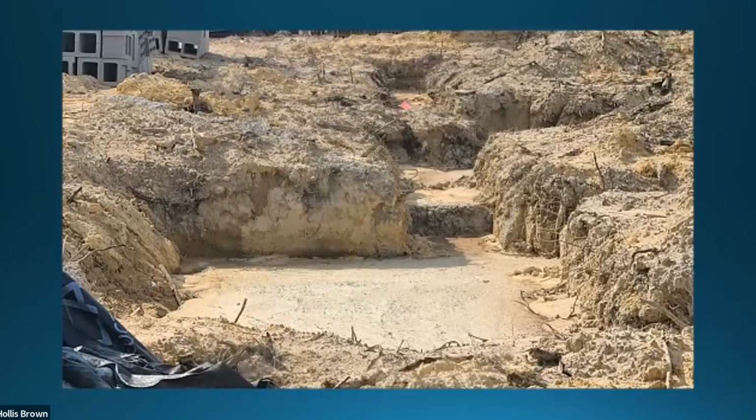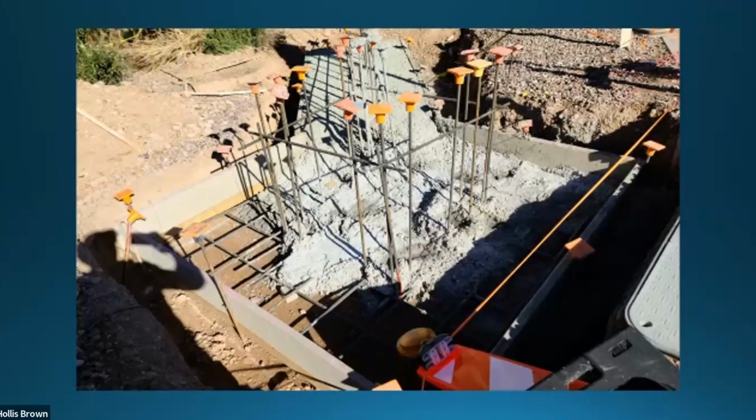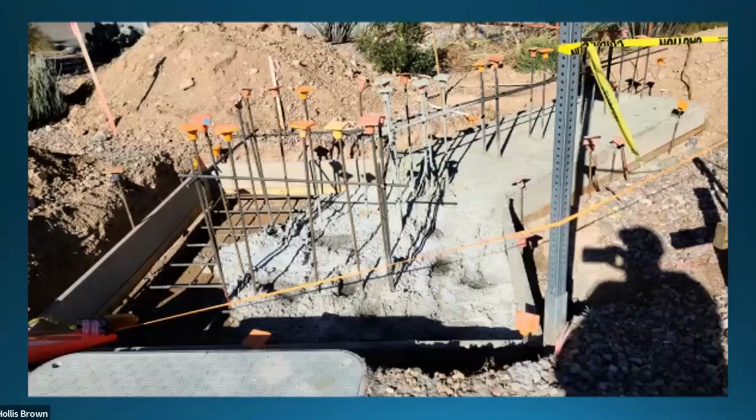But now we're on to footings. Footings always have to be installed on undisturbed soil. That's extremely important. And they should be poured all at once. You don't want cold joints. This was a concrete pour out in Arizona, and looking at this footing being poured, they stopped right in the middle of a pour. So I guess they were okay with cold joints for this particular footing, but you just really shouldn't do that.